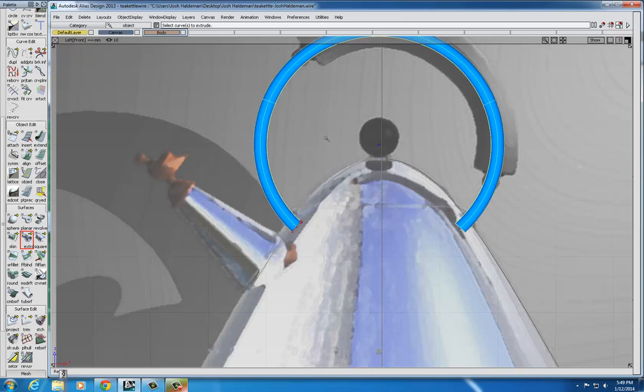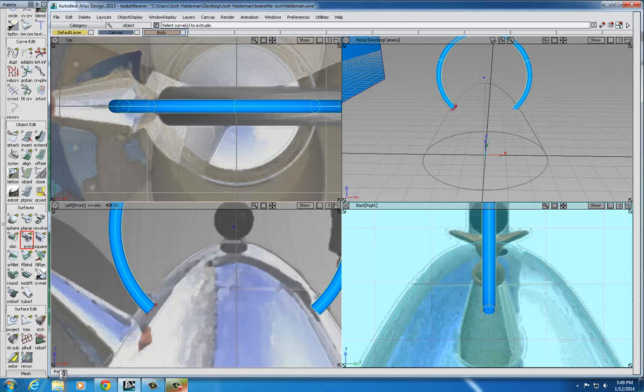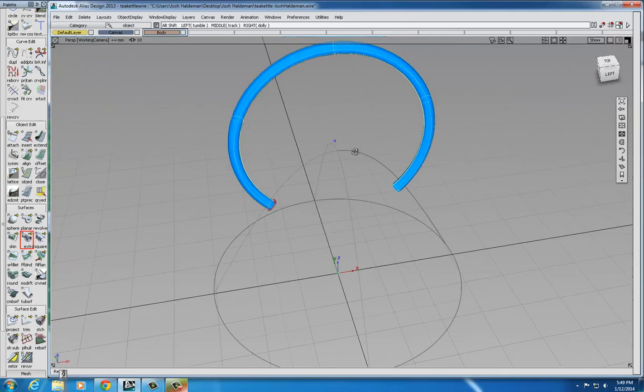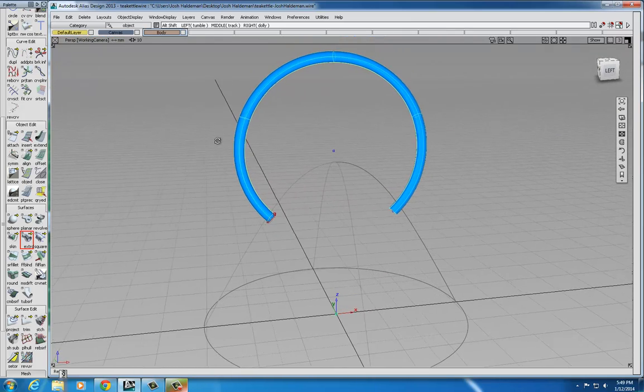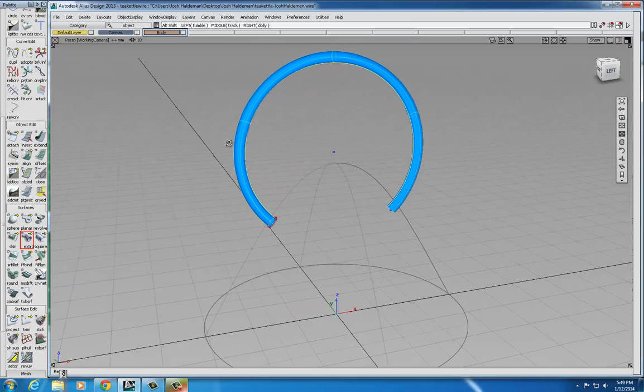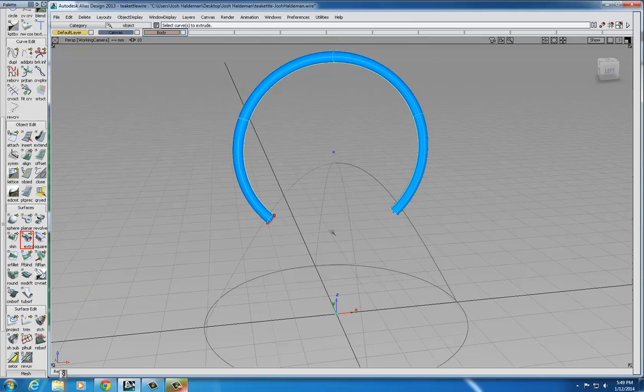When you select it, the 3-point arc and the circle that you created combine together to create this handle shape. And again, if you want to see that in the perspective view here, we'll move over there so you can see it. And that looks pretty good. It looks like it maintains its shape pretty well all the way around, and it goes onto the inside of the Teakettle body. That'll ensure that we don't see these endpoints. We don't see that it's ending before it completes the circle, and it'll have the illusion that the shape is complete.